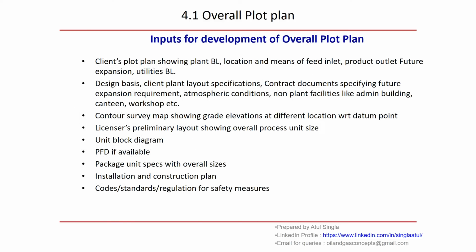So let us see what are the inputs required for development of this document. Client's plot plan showing battery limit, location and means of feed inlet, product outlet, future expansion. We need to understand from where the feed is coming, where the output product will go, and what are the future expansion plans. Then design basis,